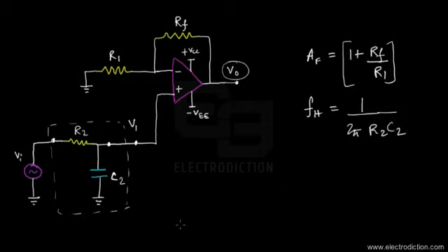So this circuit functions in a way that if the input signals have frequency components lower than the upper cutoff frequency, whenever those input signals come to the passive filter's input, it lets them pass to the input of the non-inverting amplifier. The non-inverting amplifier would then amplify them, providing a gain of AF times, to make them appear at its output as its output voltage.